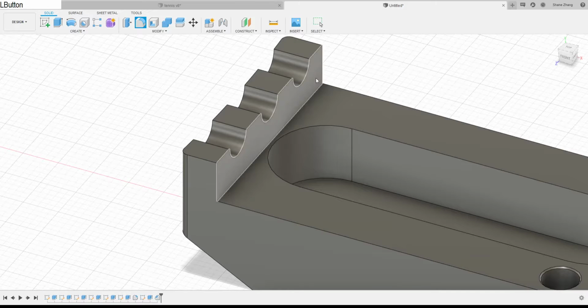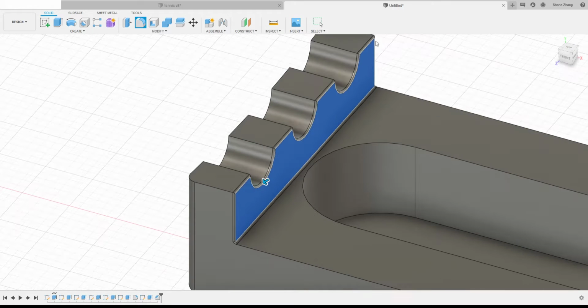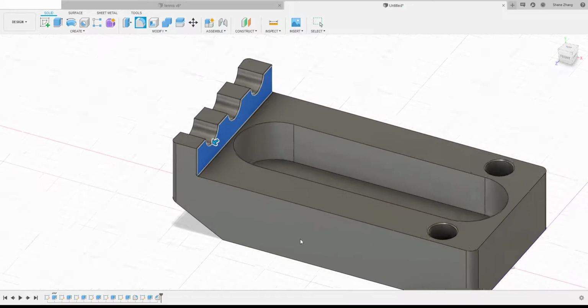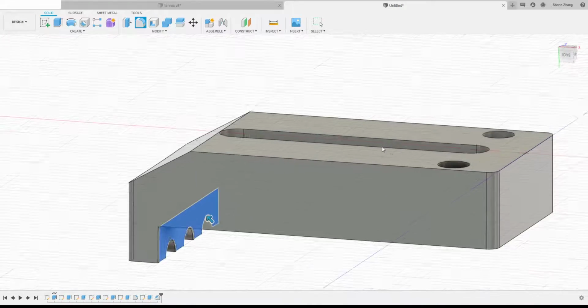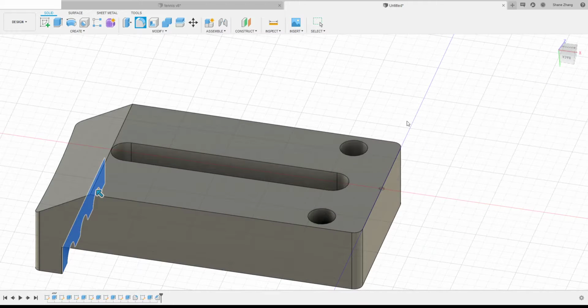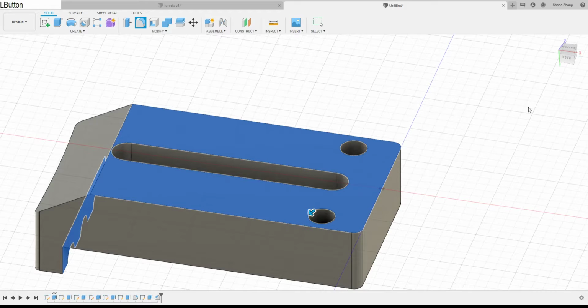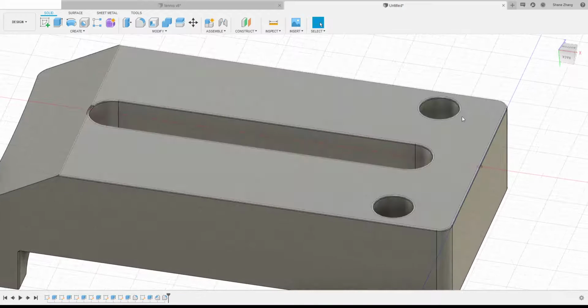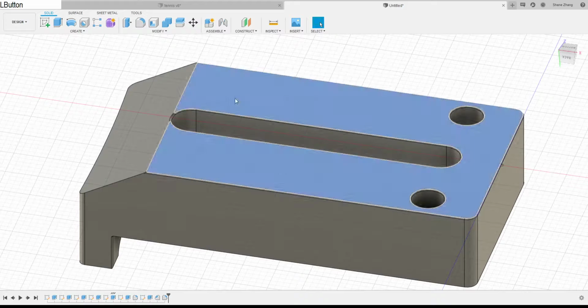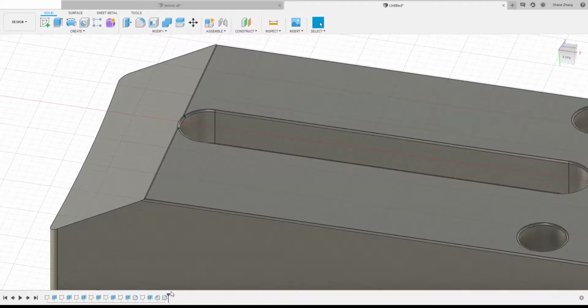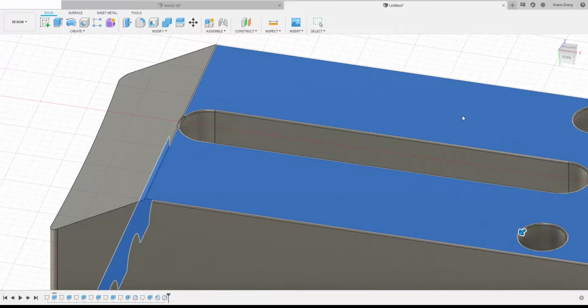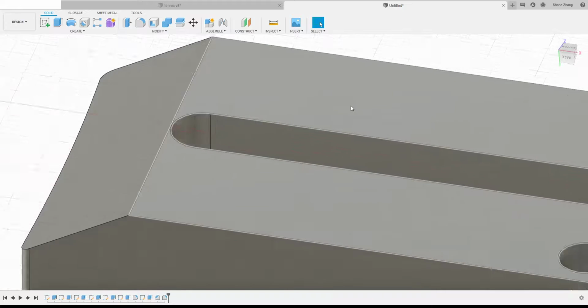So for fillets, you can actually pick a plane. It'll fillet everything around this profile, so all the edges. If I use this as an example, not necessarily true in the model, so if I pick this plane and hit enter, you can see it does a fillet on every edge on this plane, including this little thing. So that's pretty much the whole modeling process.